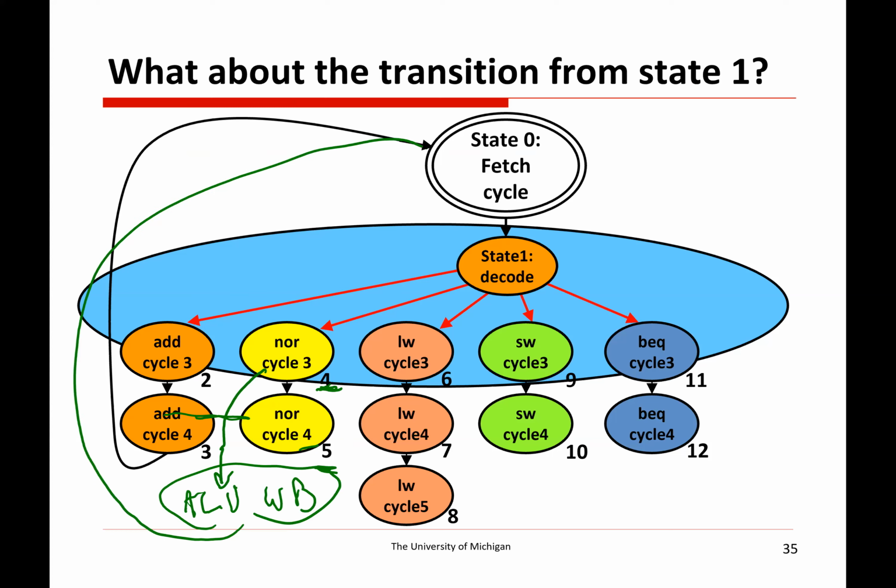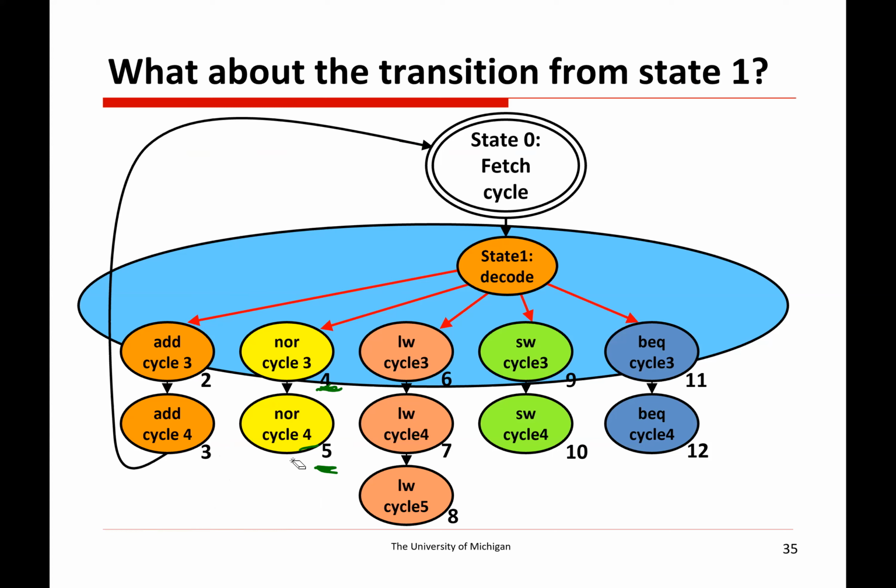You know, we could have saved an extra row in the decoder, but it doesn't really matter because we need a power of 2 anyway. So it's probably easier to understand if we just have these be 2 explicitly separate states, even though they're doing literally the exact same thing. Yep, states 3 and 5 doing the same thing, just taking the ALU result, writing it back into the register file, and then we go back to the fetch cycle.